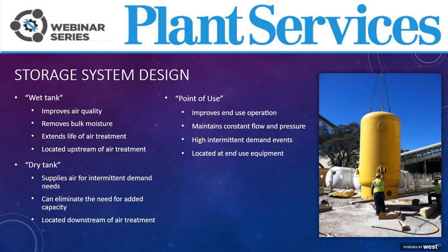Point of use receivers are great for high intermittent demand events, and you should also consider metered storage for those applications. An air audit is a great way to figure out the design for these size tanks.